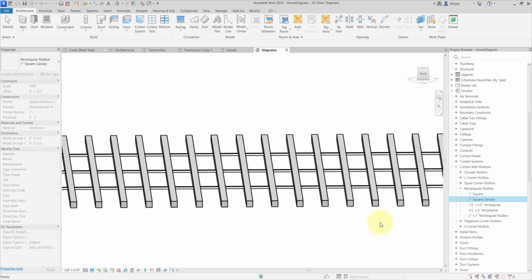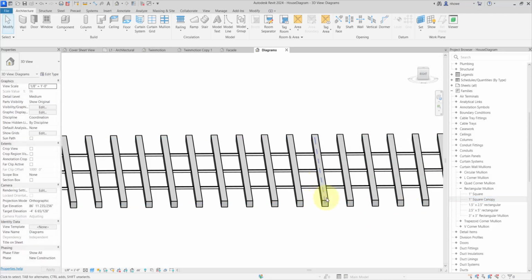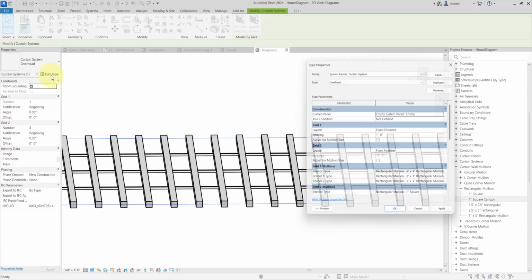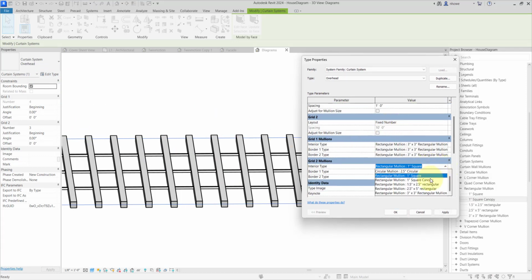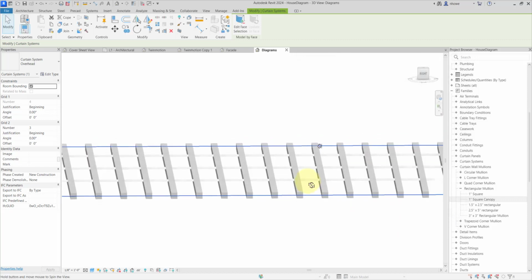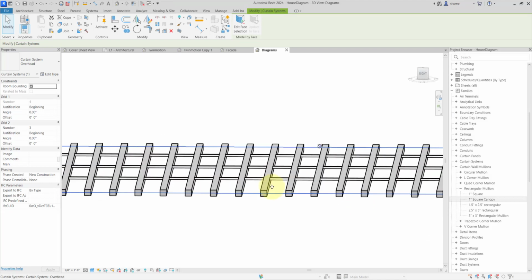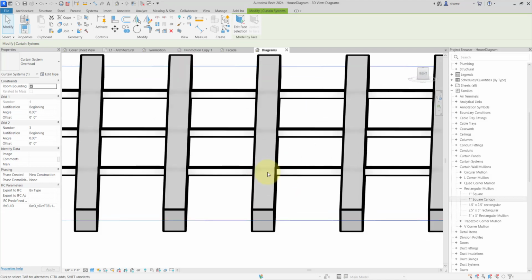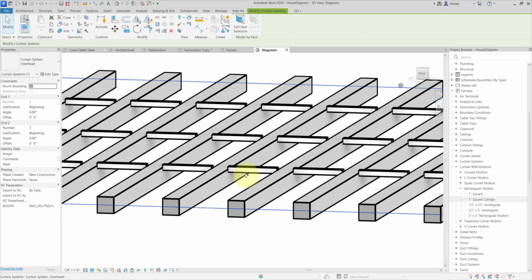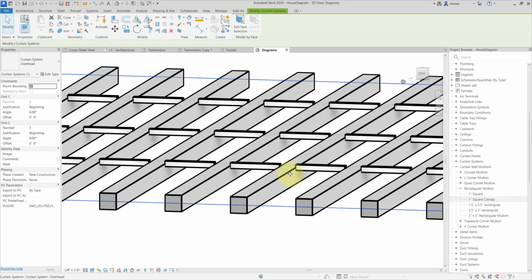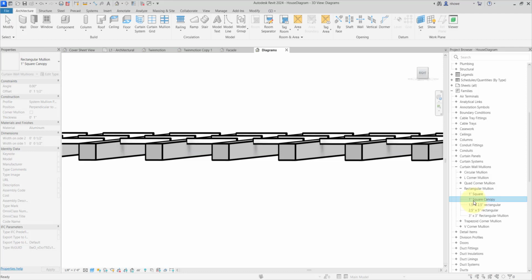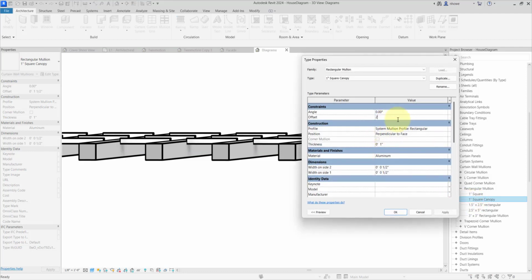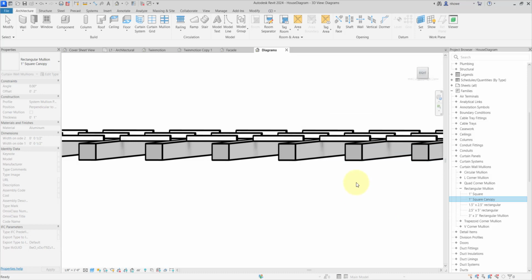And I'm going to say okay, and then I'll go into this curtain wall system and I will go ahead and apply that 1 inch square canopy to it. And you'll see it does move. It moves, but it also has this kind of gap. You can see that gap right there. So that's not exactly what I intended. And it looks like actually I needed to move it 2 inches, not 1.5. So we'll just go ahead and do that.